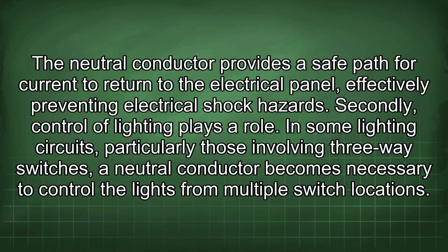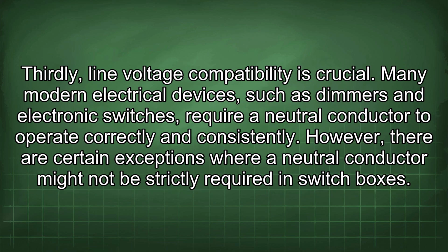In some lighting circuits, particularly those involving three-way switches, a neutral conductor becomes necessary to control the lights from multiple switch locations. Thirdly, line voltage compatibility is crucial. Many modern electrical devices, such as dimmers and electronic switches, require a neutral conductor to operate correctly and consistently.